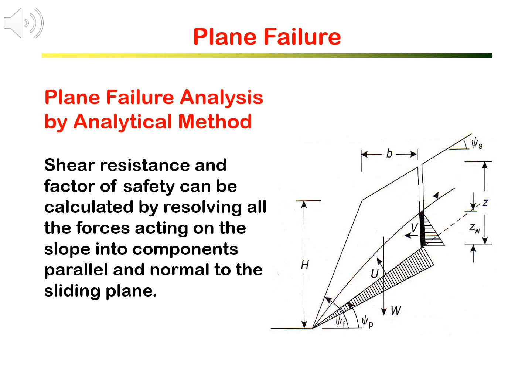The factor of safety is a ratio of shear resistance to sliding force. If the factor of safety is less than 1, the slope will slide and fail. Analytical methods can also allow for additional loads, including groundwater pressure.